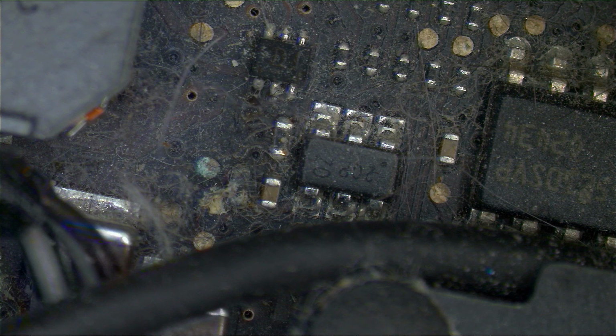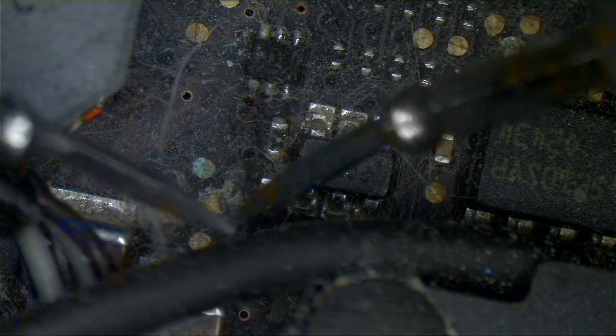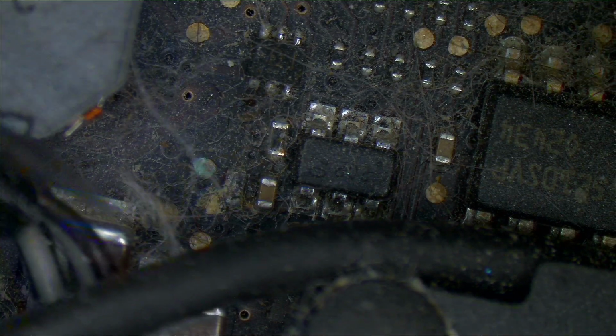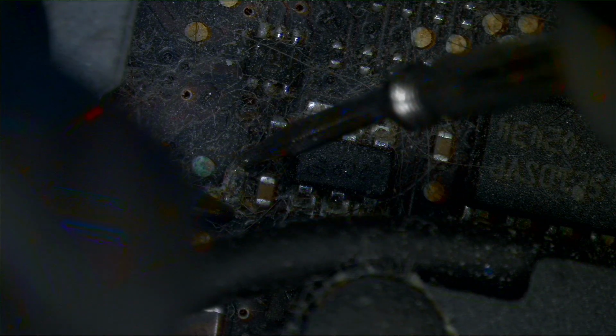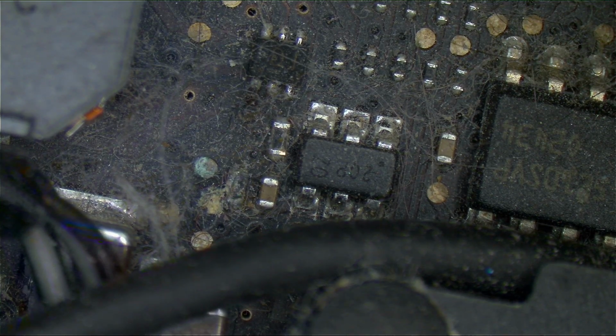Now, that being said, let's measure that resistor and see what we figure out. So the resistor that I'm looking to measure over here is going to be, let's see, R9788, which is going to be the one that's covered in some nasty looking stuff over here. So let's just dig this out, and now that resistor is supposed to be 301 kilo ohms, and when I measure that resistor, I get 301 kilo ohms. So that is doing its job. All right.